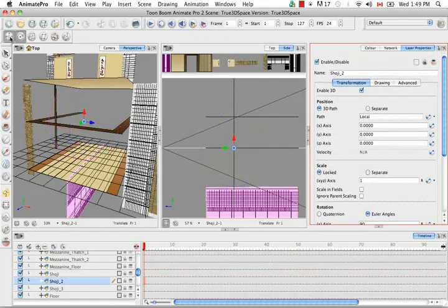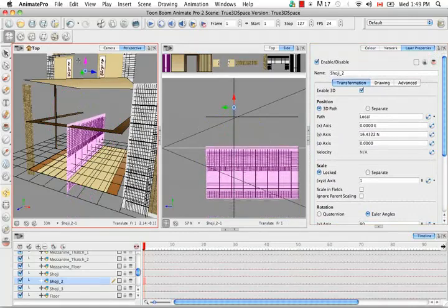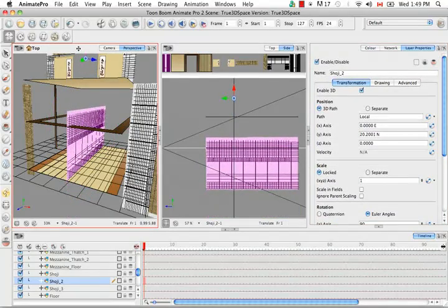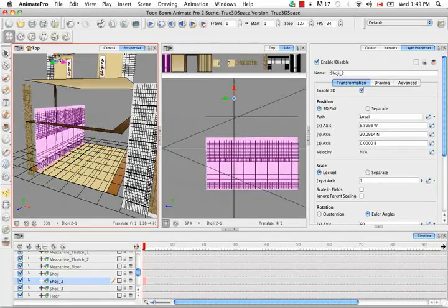So I'm going to use the Translate tool and highlight this red arrow and pull upwards. And then highlight the blue and pull this way. So you can do it there like that, or you can do it through the side and top view, which is actually what I recommend. So we're going to do it that way for the next side. And as you can see, the values have changed here again. Our wall has been moved west and north of its rotated position.